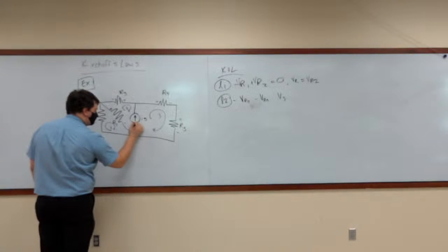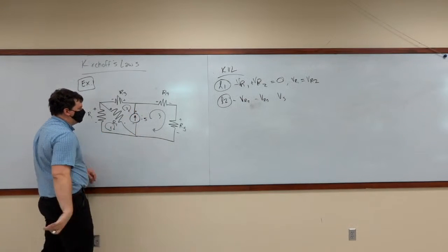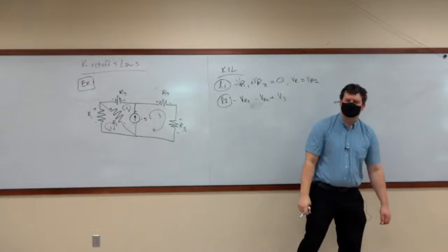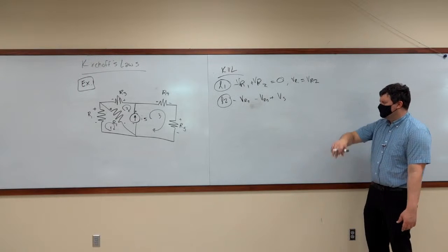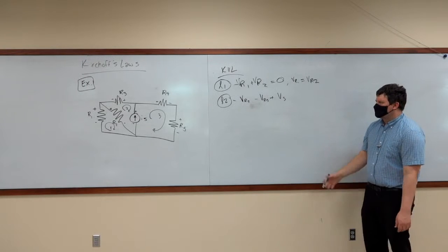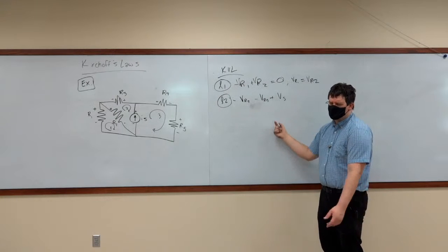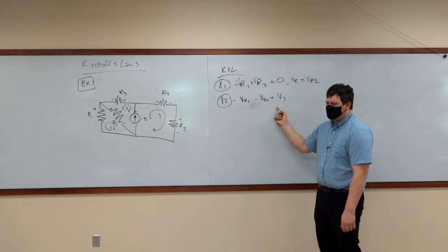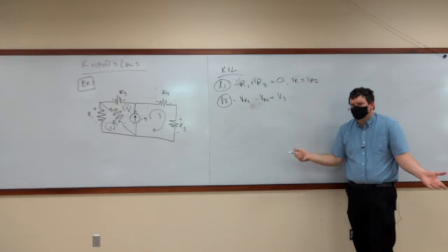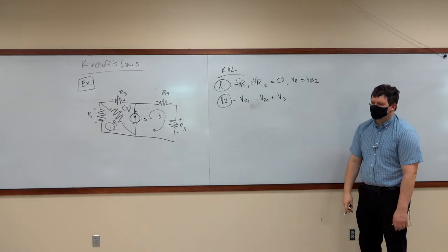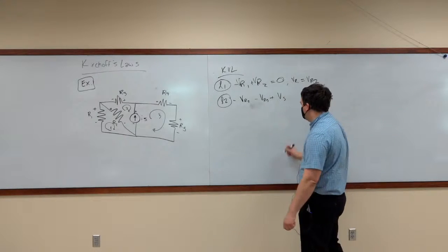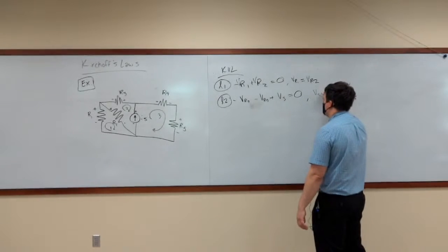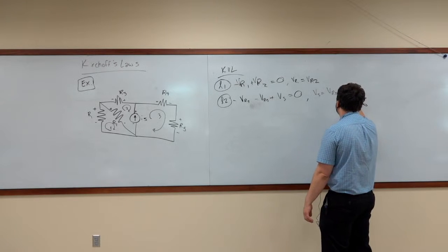I guess we didn't really write the negative and the positive end, but it touches the positive end, which means this is actually, according to the configuration that we have, considered positive by going around clockwise. Now we could have flipped all three of these, done them the normal way, just by drawing it a different way. And then we would have ended up with this a negative, these two positive, which is what we're used to. Yes, you can do that, Jeremy. That's perfectly valid. But you have to get the right equations. So we can rewrite this one as VS is equal to VR2 plus VR3.